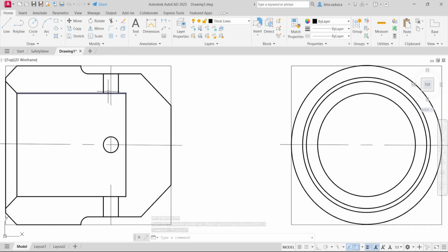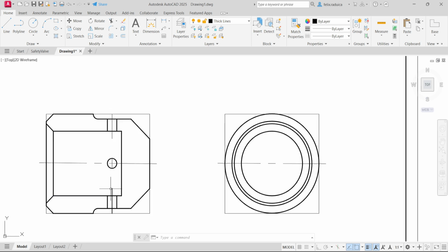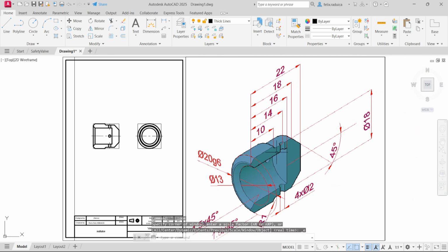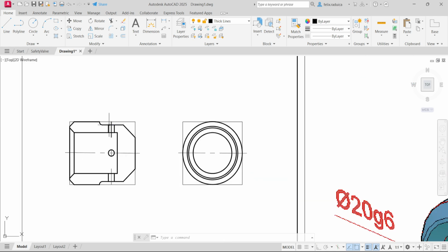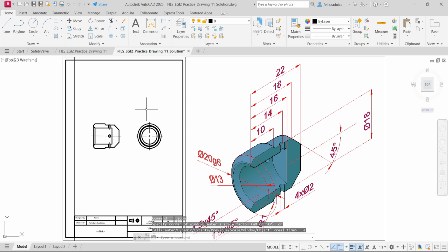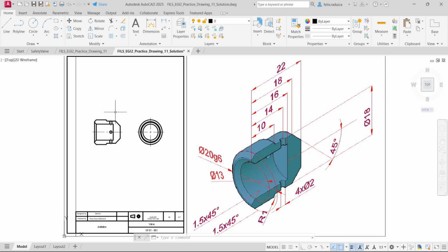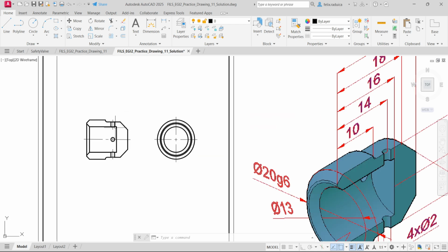Now we have to trim these two. And we also have to trim these two and deal with the intersections that happen here. As you can see, they are not straight lines because they have two cylinders that intersect each other. So here you should have some curved lines. Let's consider that we have this projection here, and we also have these two holes here.